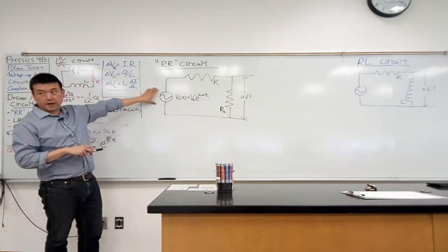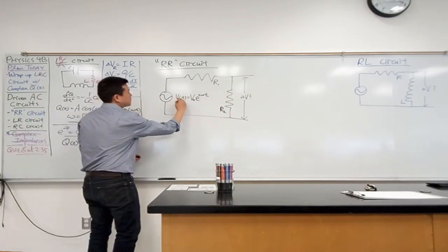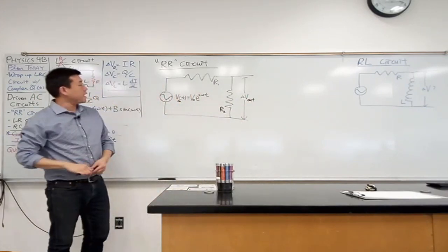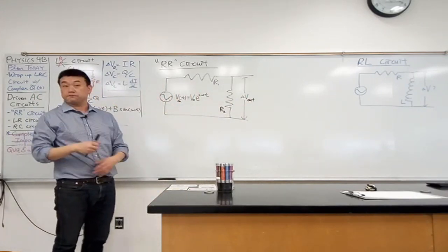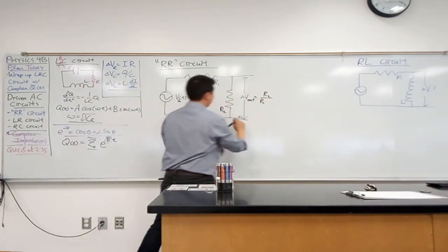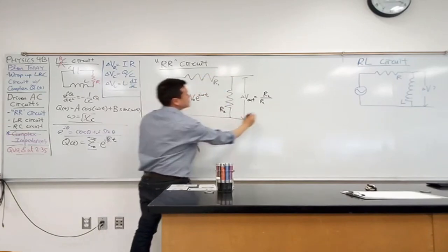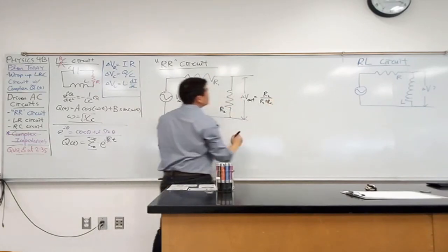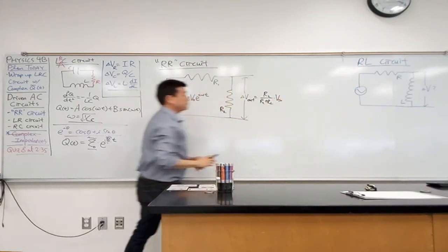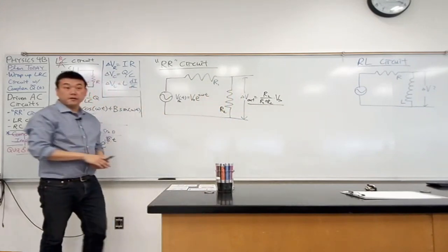So we call this a voltage divider because when you work through this circuit, call this voltage in, call this voltage out, the formula for voltage out ends up being this pretty simple formula: R2, the resistance here, divided by the total resistance, R1 plus R2, times the input voltage. This is the formula that you have seen, you have derived.